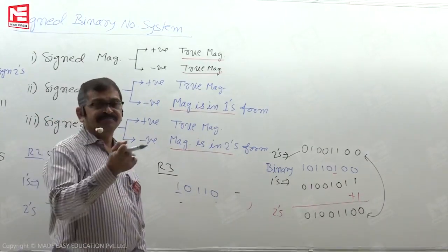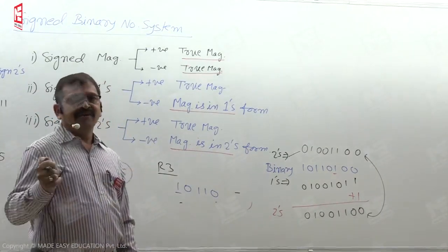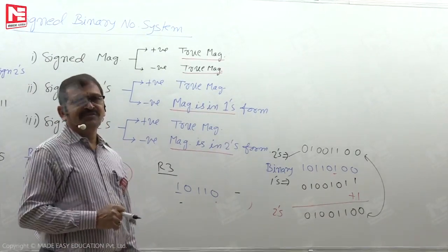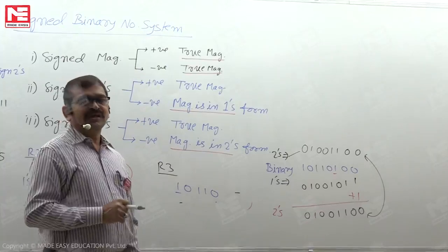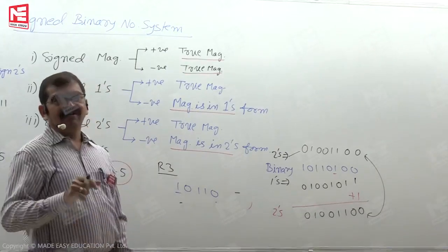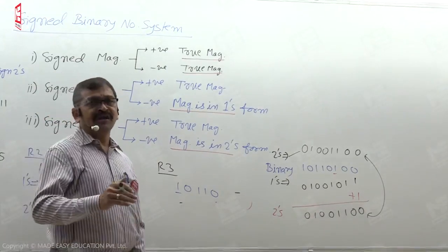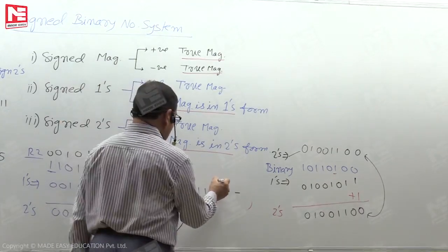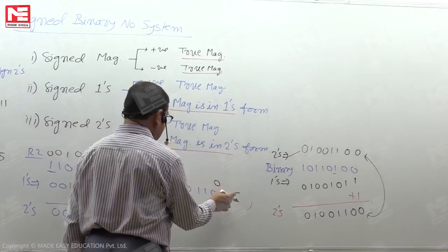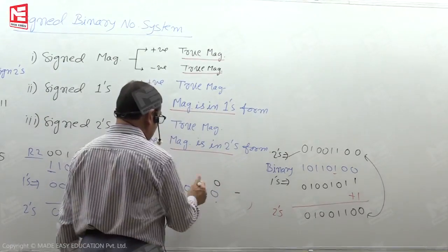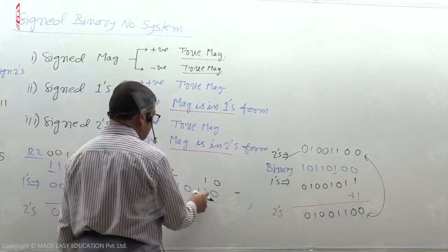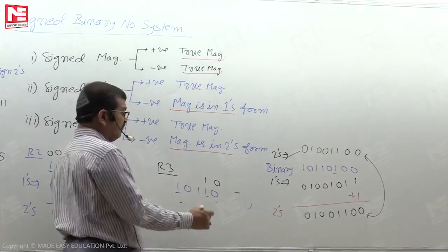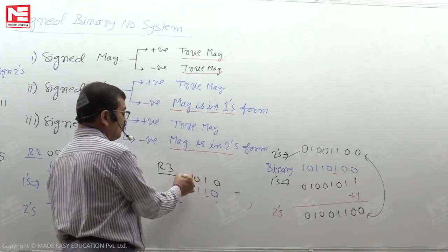Whether it is a 1's complement case or a 2's complement case, once the number is negative, to read the true magnitude, after identifying the sign, we perform the complement operation on the total content of the register. While performing 2's complement here, we scan the number from LSB to MSB, right to left. We read the bits as they are until we read the first bit that is 1. After reading the first 1, we perform bitwise complement.